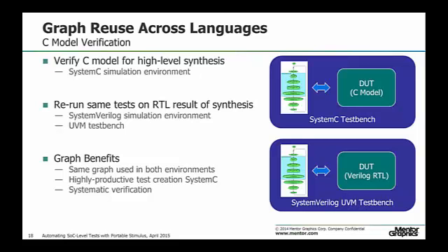Typically, this would be verified in a SystemC simulation environment. So we could create a graph that drives our SystemC environment. Then, after synthesis, where we have generated the RTL model, the same graph could drive a SystemVerilog environment or a UVM test bench, but it would be the same high-level graph that would be reused to do systematic verification in both environments.